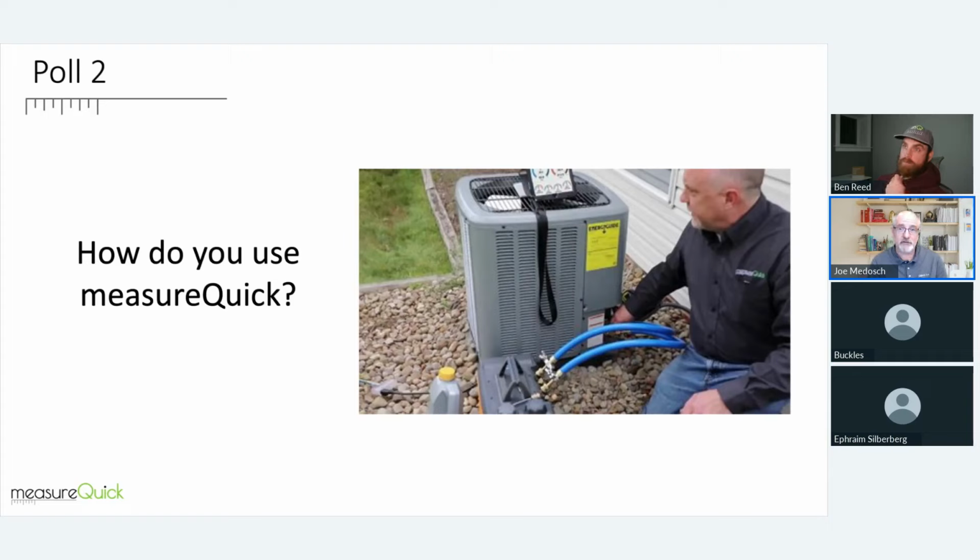If for some reason your approach is above the outdoor temperature, then there's a problem, either potentially a probe problem or a condition in the system where your refrigerant line is now not providing correct information. So the approach is only on the liquid line. It's the liquid line compared to the outdoor temperature that is the definition of how we calculate the approach.